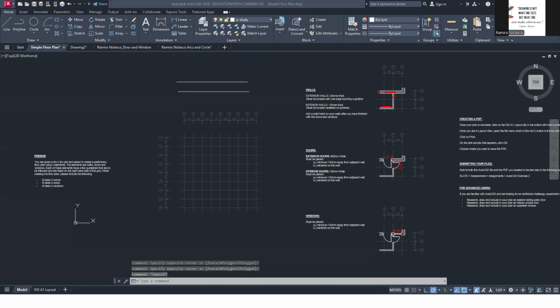I had a question regarding AutoCAD. You know how when you're typing something like line, when I'm at home, I type it down here, but I don't get the little icon here. Where do I see that? You go to this customization button. Make sure dynamic input is on. Here. Make sure that's on. So you'll see it here and click that. All right, so then that would give me that little option. Yes. Thank you.